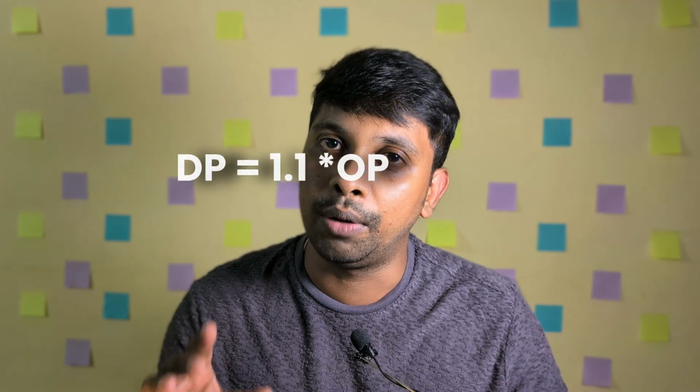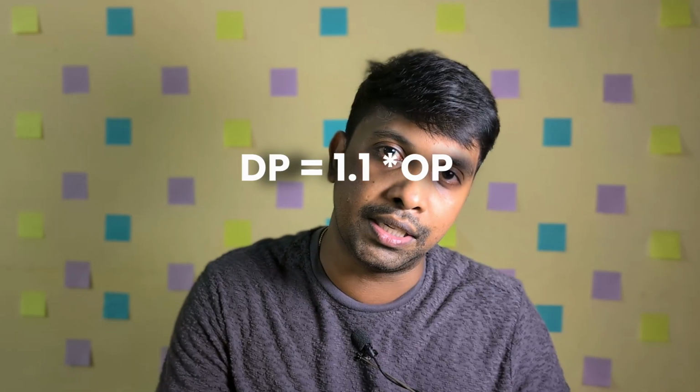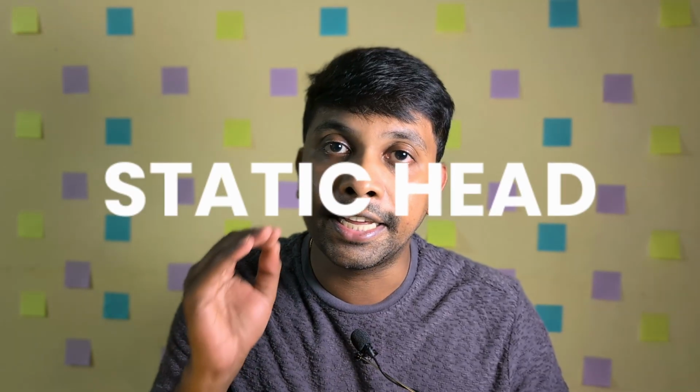And finally, I will give you a bonus tip on how to calculate the design pressure. Normally engineers take 1.1 times the operating pressure, that is, 10% higher than the operating pressure, for the design pressure. Yes, we can do that, but you have to calculate the static head of the vessel.